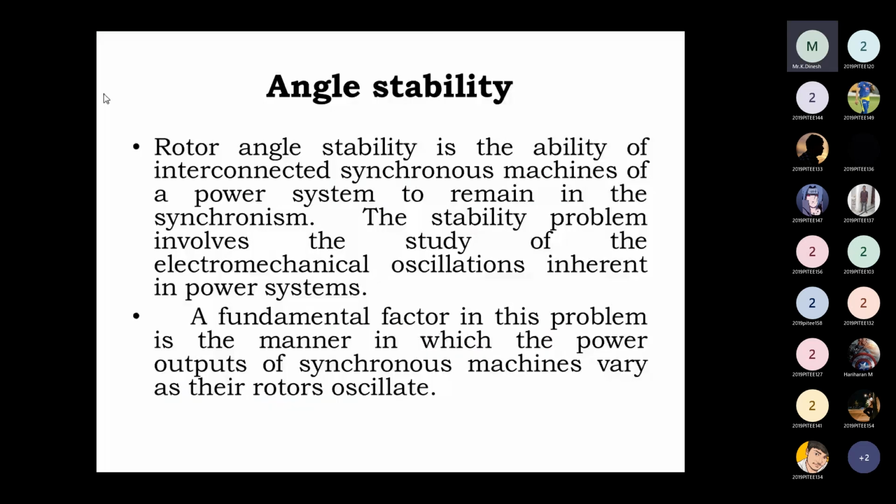So the rotor angle stability is the ability of the interconnected synchronous machines. Interconnected in the sense we have to consider our mechanical system also. Obviously, the synchronous machine is connected with your mechanical prime mover. So interconnection issues may happen in your angle maintenance, to remain in synchronization. So the torque balance, as I said in the diagram, we need to maintain. So the stability problem involves the study of the electromechanical oscillations inherent in power systems.